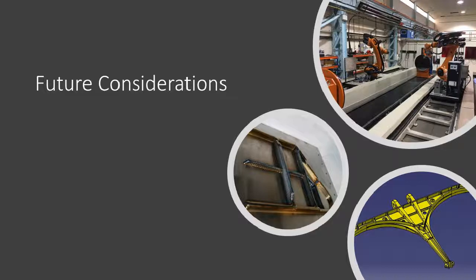Okay, that's great. And is there a need to do much post-processing? Yeah, so certainly it depends on which channel you go down to create the pattern for the part. From the scanning side, which is something I got acquainted with during the research for this webinar, absolutely, because as I mentioned, the 3D scan is literally a facsimile of the original object. So it picks up any flaws, and therefore the scan itself offers little utility. Now, if you're designing from CAD, then obviously the item that you draw should be in its finished state, as per any conventionally manufactured reductive part.